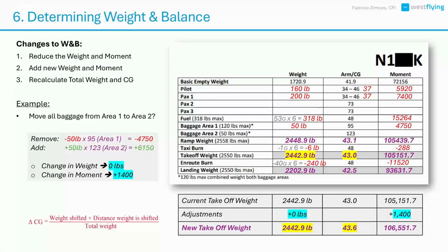What if you, the pilot, calculated all the weight and balance beforehand? Everything was fine, but then, when loading your payload, you realize that you need to make adjustments? For example, let's say the shape of the baggage will not fit in the station you calculated previously, and you will need to move it further aft. Do you need to redo all your calculations? Yes, but you don't need to recalculate it all.